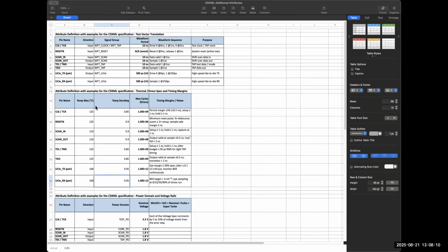And then the scan in and scan outs: at what time relative to the clocks you want to force it, and what time you want to do a strobe. These examples are given with just arbitrary values, as a placeholder.